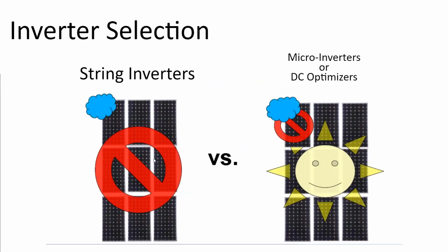Now, that doesn't mean that the panels produce more electricity in the shade. You should not have a shaded solar array. It does not work in the shade, or if it does, it works substantially less than unshaded. But there are shadows that are either unavoidable or temporary. So a chimney might just shade one or two panels near the chimney and that's it. But if that has ramifications on the rest of the system, then you cannot go anywhere near the chimney. There might be a portion of the roof that is sunny for eleven and a half months out of the year, but for two weeks in December, it's shaded by the tree line. And it might be a good decision to install there anyway.